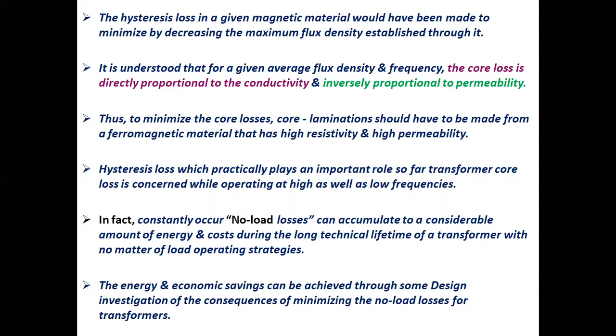Hysteresis loss practically plays an important role as far as transformer core loss is concerned, while operating at high as well as low frequencies. In fact, constantly occurring no-load losses can accumulate to a considerable amount of energy and cost during the long technical lifetime of a transformer, no matter the load operating strategies.